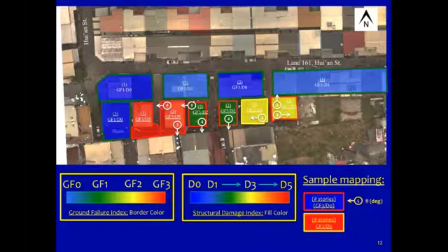Structures within the interior with visible significant structural damage graded as yellow through red, red, for example, here and here, and yellow color-coded damage here, were mostly associated with structural discontinuities, primarily stemming from those discontinuities at the foundation, and often associated with lightweight single-story addition regions. As we'll see in just a minute, we'll look at a few vantage points walking into this alleyway, looking at a moderate damage situation, and looking at the backside for comparison.